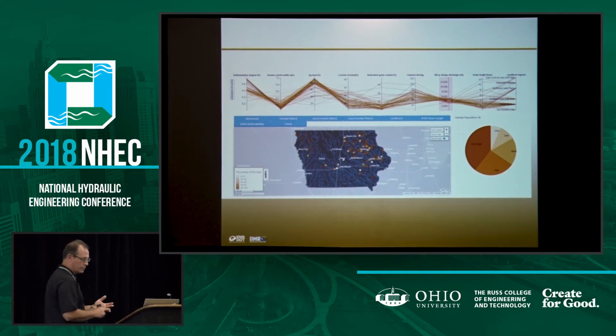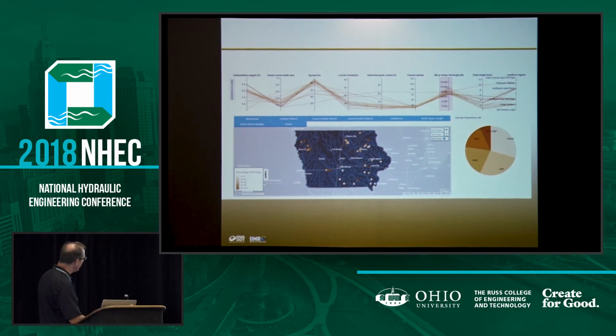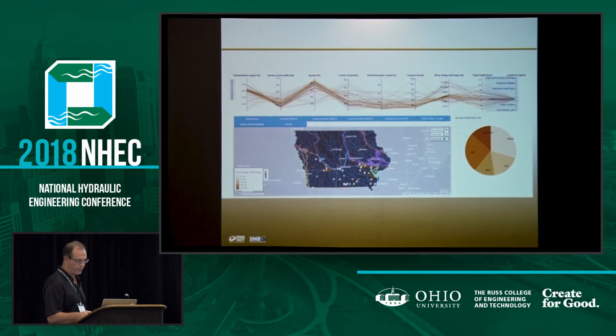The stream to culvert width ratio is a big factor. Okay? But notice when you just get a little bit higher in flow, then it starts to mitigate again, where it's not as much of an indicator for sedimentation of the box culverts. The third one, the main third driver I want to talk about is the landscape.